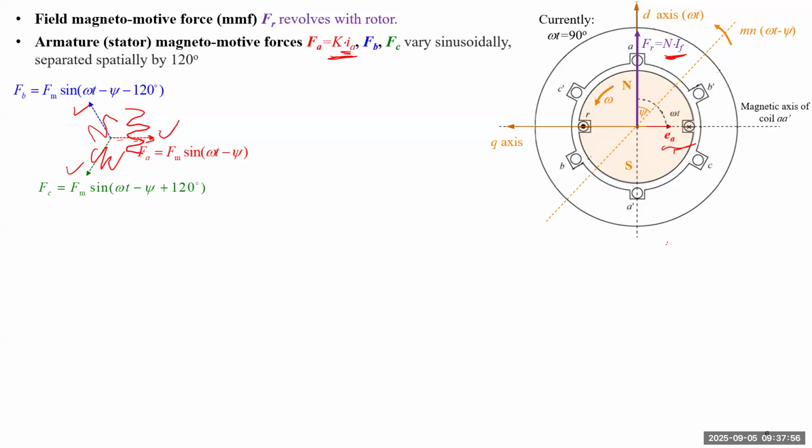So we have to formulate each one, then calculate the total magnetic force. Together they become something we call FS, the stator winding magnetic force. We don't want FS to be too complex, because we're going to need FS together with FR to determine EA, the phasor for the stator winding A. Everybody follow? If you're lost, just let me know where you lost it, because we need to make this slide even busier.